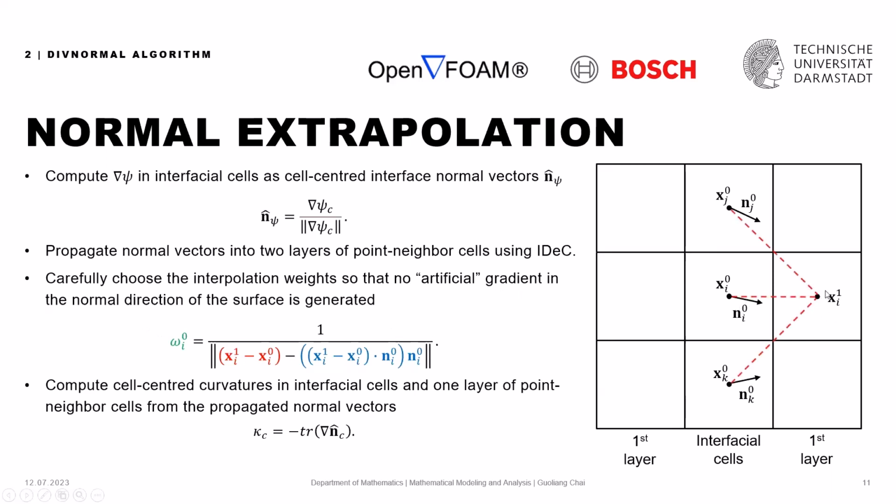Usually when we are doing inverse distance weighting, we use the red lines as the distance, and one over this distance as weighting. But imagine if this point is exactly on this blue line, the normal vector on this point should be exactly as this one. So we don't want any variations along the normal direction, so we get rid of the weight that comes from the normal direction, the blue one. We use the red one minus the blue one as the final interpolation scheme, the green one.